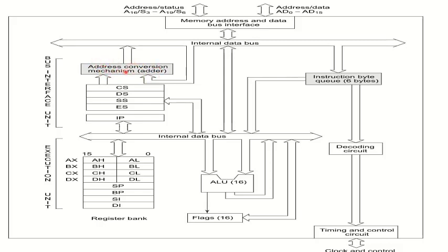This address generator will generate the 20-bit address with the help of the code segment and the offset, that is, the different index registers and instruction pointer registers. The instruction pointer, as discussed in the last class, is a 16-bit register that holds the address of the instruction to be executed next.